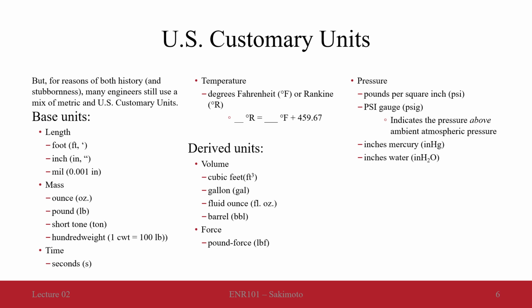So when you have your car tire that is at 40 psi, or let's say 30 psi, 30 pounds per square inch, in most cases that is 30 psig. It means 30 psi above the ambient pressure in the air, which for sea level is 14.7 psi. Things that you don't necessarily need to measure, but you'll tend to learn them as you go along.